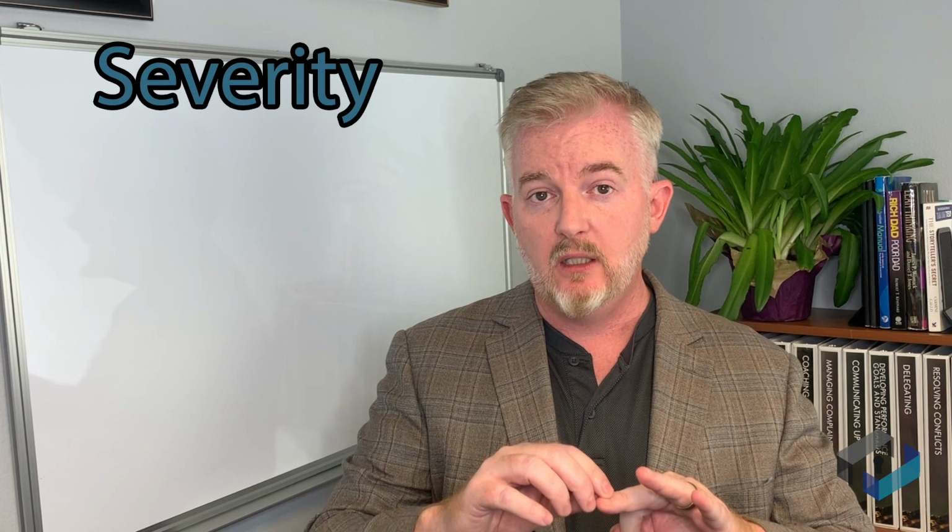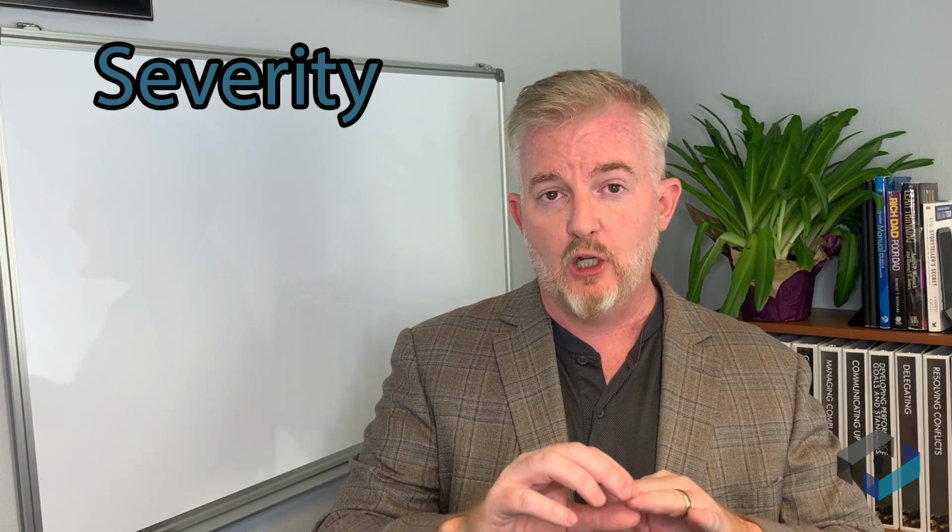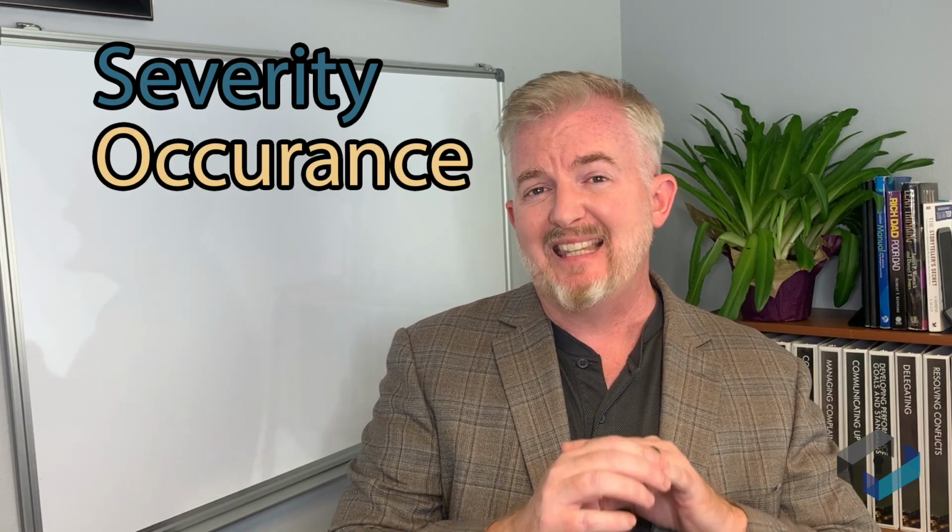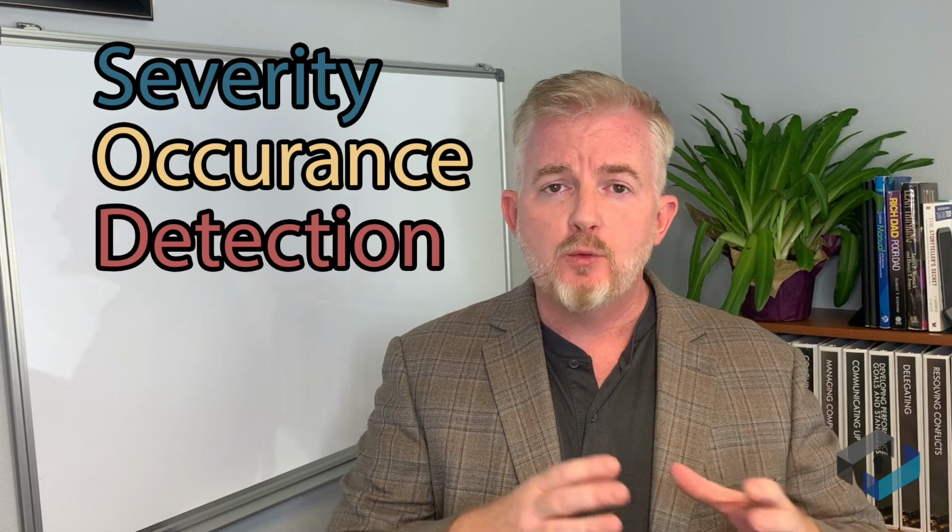Now, effects analysis is broken up into three parts. We're gonna look at the severity of the issue, the occurrence of the issue, and the detection. Right, and each one of these gets a score of 1 to 10. In essence, let's break this down so we really get this. In essence, we're getting a holistic view of how bad this particular issue is, how often it can happen, and really, is it in our control or not?